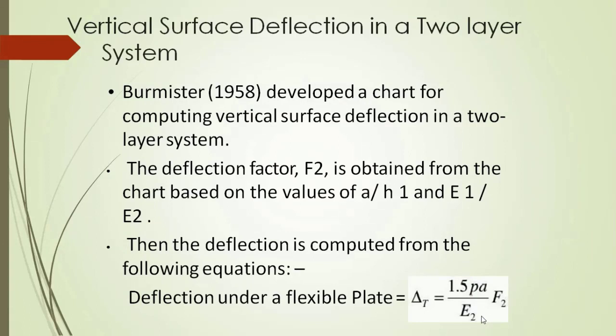So after that, the comparison of the vertical stresses distinguishes between the Boussinesq single layer system and the Burmister two layer system.